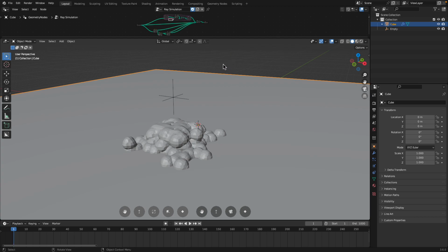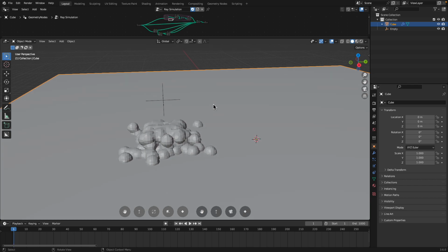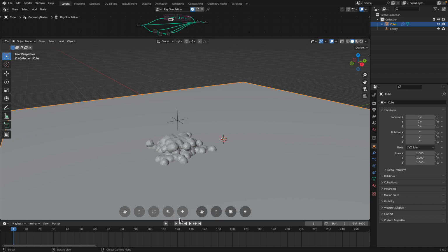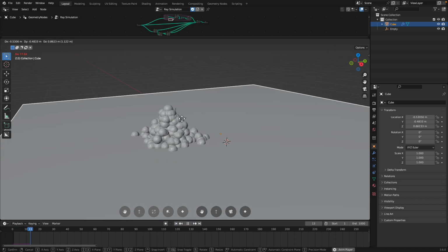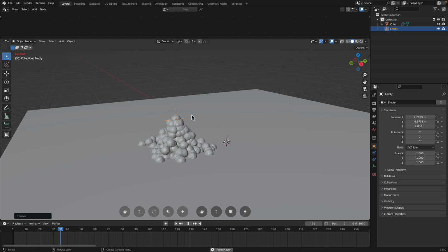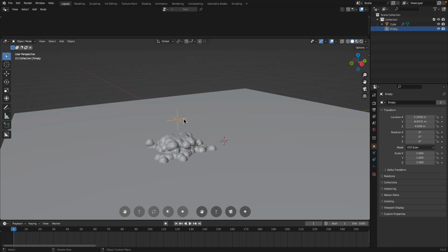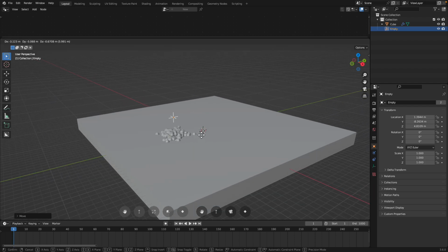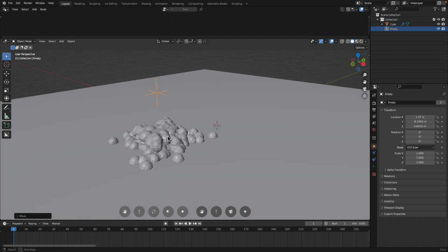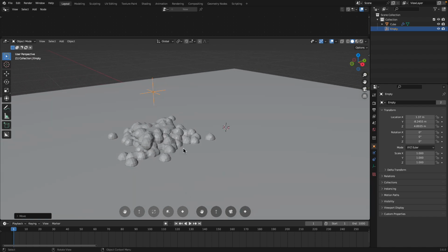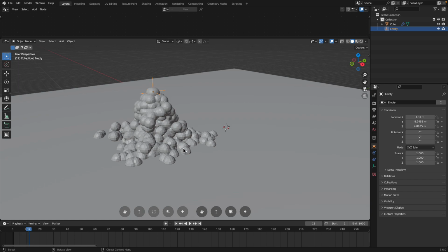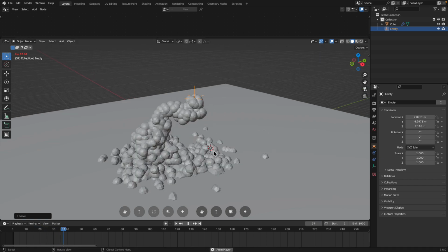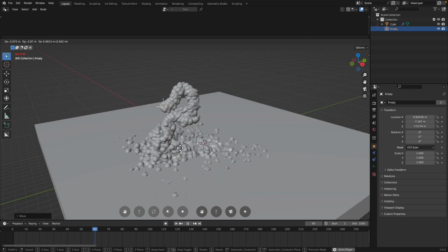In this episode, I want to show you this simulation node setup using geometry nodes in Blender 3.6. It's a simple setup. Basically, if I hit playback, you can see I have this empty. On frame 1, if I move around the empty, you can see there's a bunch of particles, or a structure, that if I step frame by frame, is kind of spraying particles.